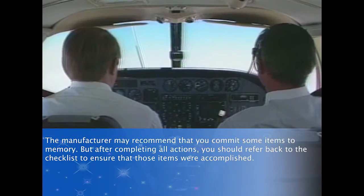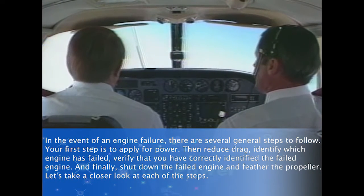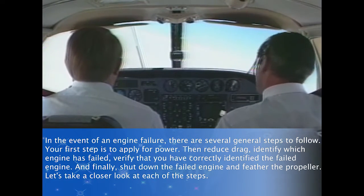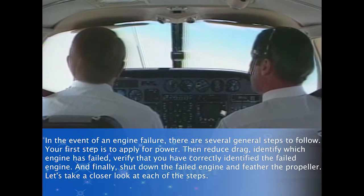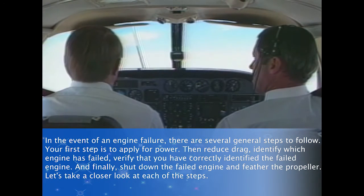In the event of an engine failure, there are several general steps to follow. Your first step is to apply full power. Then, reduce drag, identify which engine has failed, verify that you have correctly identified the failed engine, and finally, shut down the failed engine and feather the propeller. Let's take a closer look at each of these steps.